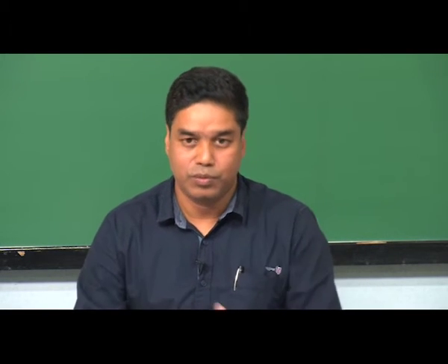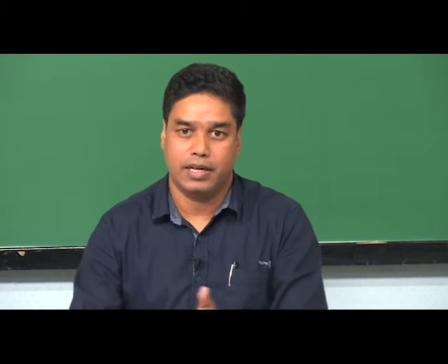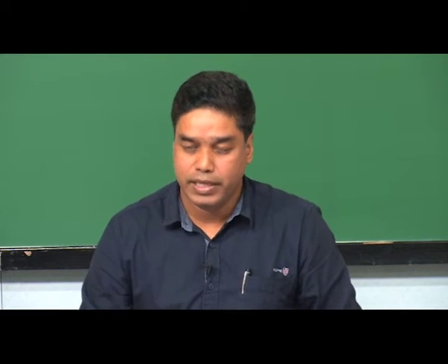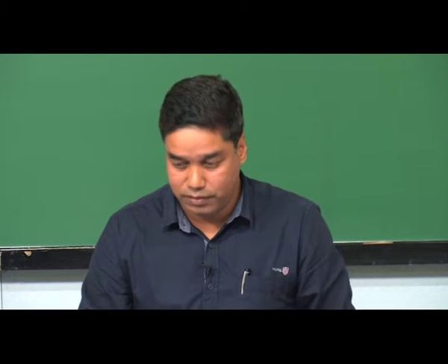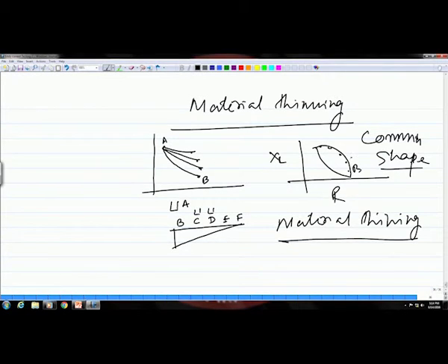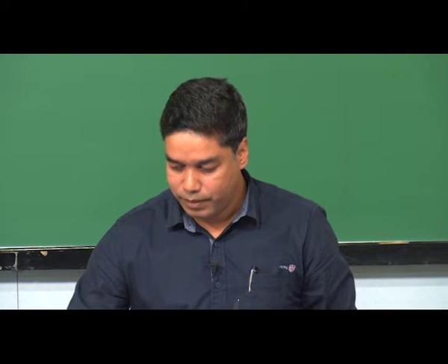in this case. As you move from B to F, there is a gradual decrease in the thickness, and that is being indicated by a change in the lift off curve. And when you connect the endpoints of all these lift off curves, you will see this comma shaped curve like this, and this will indicate the material thinning. So, this is how this particular technique can also be used to indicate material thinning in a given part.